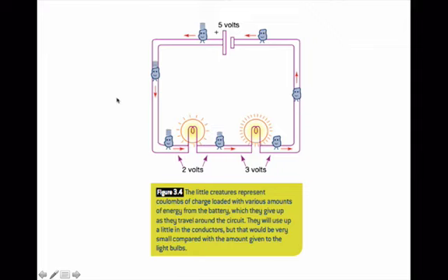Right, so I've just repeated this diagram just so I can scribble over here a bit. So this is where people get confused with measuring voltage. If you measured voltage between these 2 points here, this charge is going in with 5 joules of energy and coming past your second point with 5 joules of energy. Therefore, your voltmeter is going to measure 0 volts. The trap people fall into is they think, oh, 0 volts means there is no current flowing, there's nothing happening in this circuit, and that is obviously wrong.